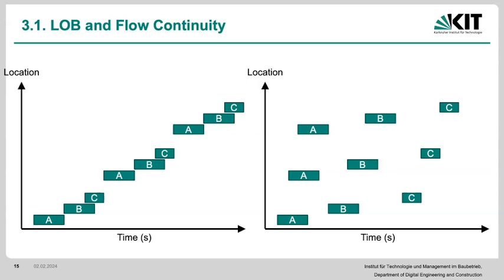This could be a highway, this could be buildings that are going to go up. So the activities can go one after the other, and we can continue them as well if we reorient them. What does that mean? That looks something like this. If we have activities A, B, and C, where activity B is a successor of A, and activity C is a successor of B with some overlap there, and then one after the other for different units.